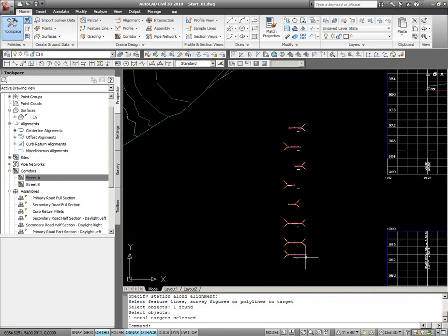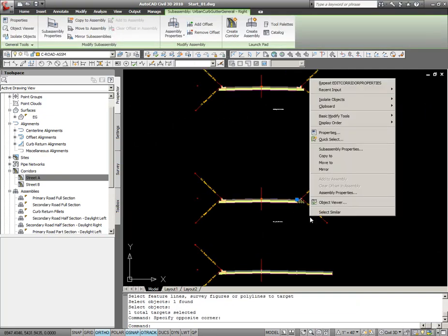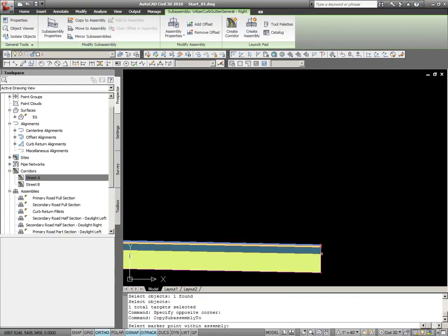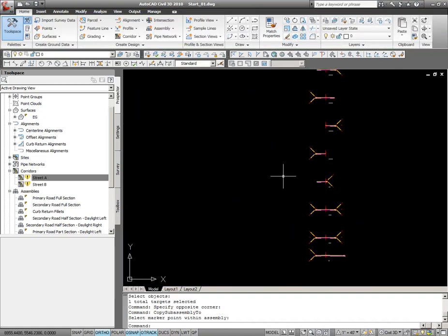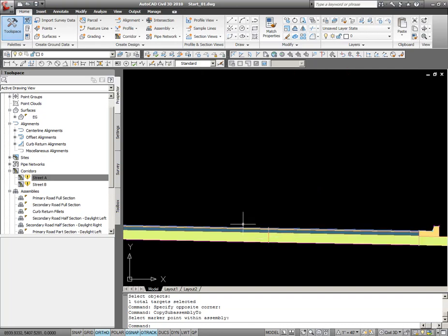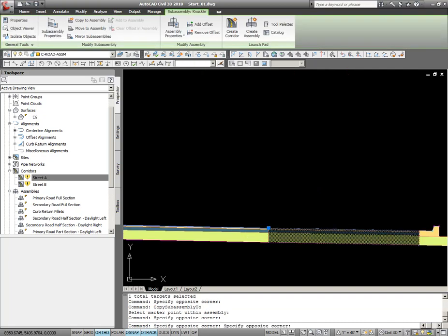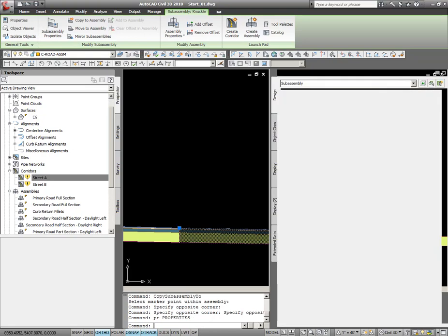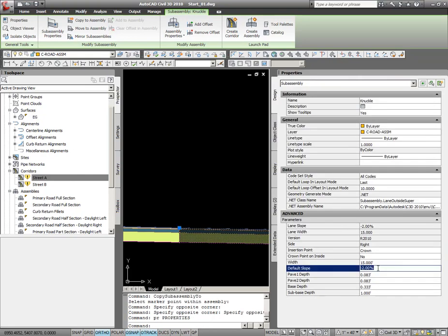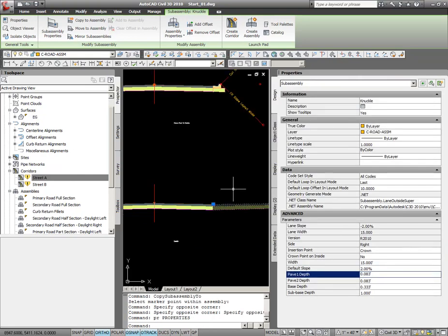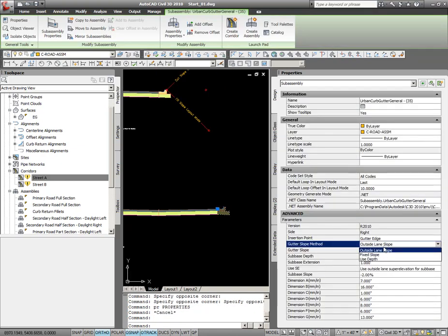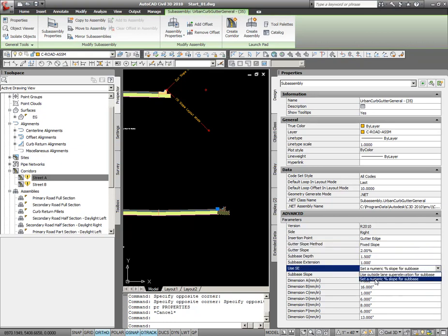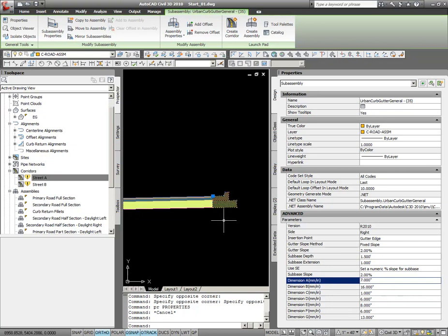Now, just to show you what it'll look like, if I copy this to that right there, and you'll see here, I'm continuing the slope down. I'm going to want to come in here and adjust that default lane slope instead of -2 to a +2 so that I can drain it back to the street. Do the same thing for this curb assembly. There we go.